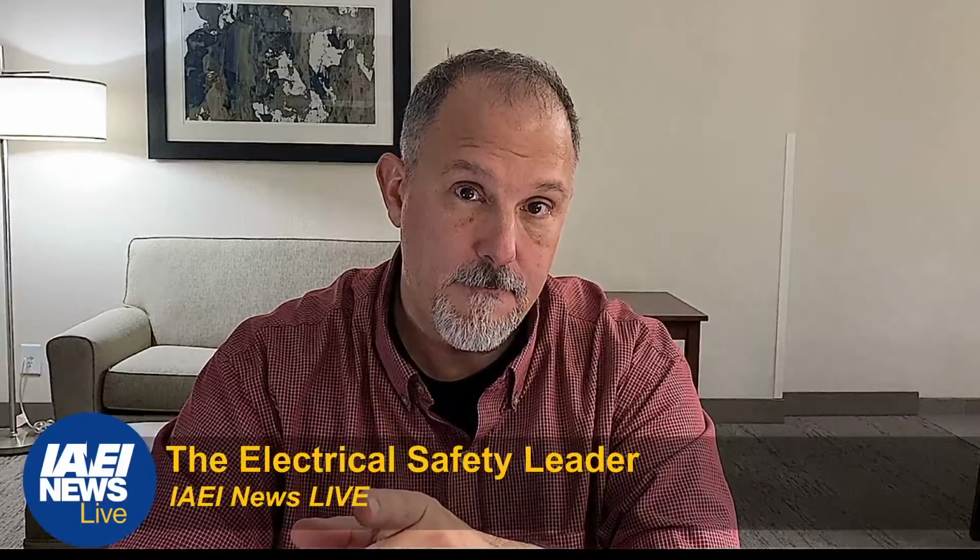So we will complete our discussion and select the overcurrent protective devices. We're not going to worry about selective coordination at first, and we're going to do an incident energy calculation, and then we're going to selectively coordinate this small power distribution system and do our incident energy calculation again. Then finally, we're going to compare our answers. So I hope you will stick with me throughout this process.